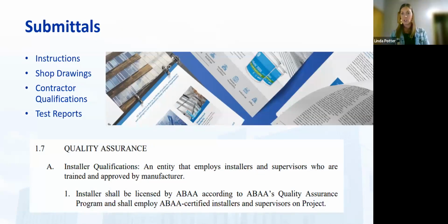In terms of submittals, when you get to your submittals in part 1, I think it's just important that we understand what we're asking and that we kind of go through this for a minute. So in some packages, some projects we've looked at, we see shop drawings being asked for, which is interesting because some people think that means manufacturer's suggested detailing, or the Air Barrier Association of America's detailing, where we're providing some ideas of how we're going to do this. Some projects actually want specific shop drawings of their project with as-built conditions showing how they're going to manage all of the details on that specific job.